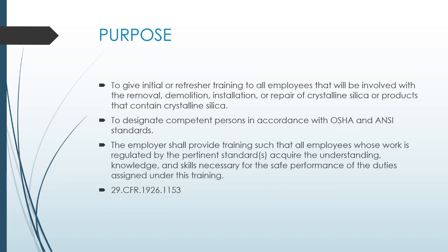The purpose of this training and all other MECO safety training is to give either initial or refresher training to all employees that could be involved with crystalline silica tasks or materials that contain crystalline silica. Under the standards, we are to designate competent persons in accordance with OSHA and ANSI standards. And remember, a competent person is someone who has the knowledge and skills necessary to identify and recognize a hazard, and then has the authority to do something about it.